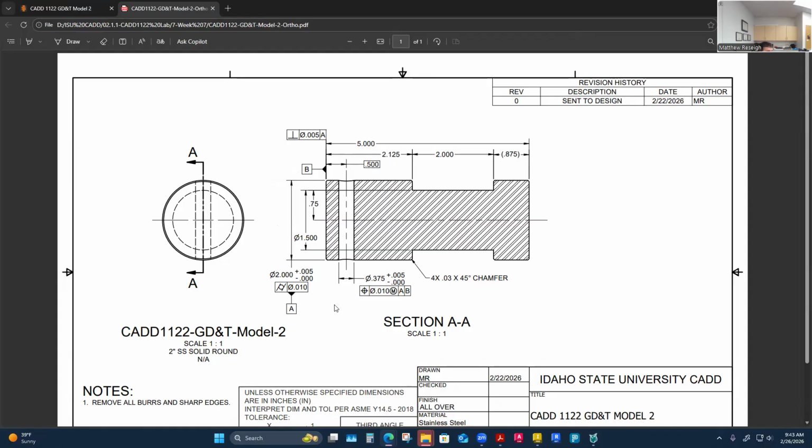So yeah. And then B would just be this left side surface, essentially the front largest surface, that I'm holding perpendicular to the datum axis, datum A, by 5 thousandths, 10 thousandths there. And I'm just controlling a hole from all that. Oh, and this is cylindrical. So this is a cylindricity form control on datum A.